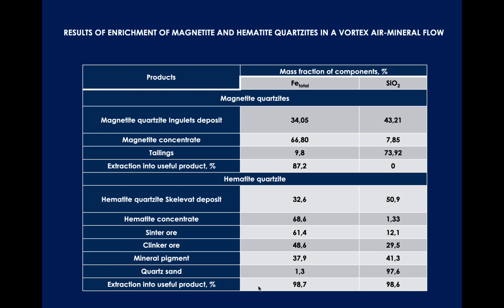The fourth, all minerals, magnetite, hematite, goethite, lepidocrocite, hydrogoethite, and hydrohematite differ in hardness, specific gravity, and morphological features. This improves the quality of iron ore concentrate. The content of silicon oxide and aluminum oxide in it is no more than 2 or 3% in total. This is in line with the standards of metallurgical companies. Minerals with a low iron content are used to produce other marketable products: sinter ore, clinker raw materials, paints, etc.